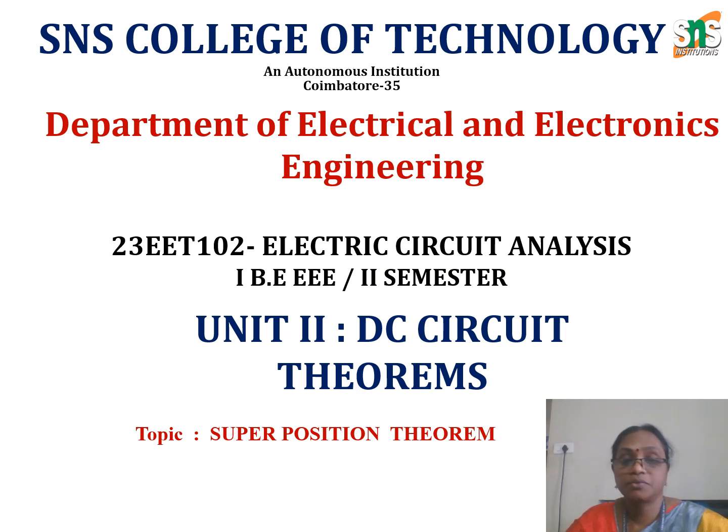I think in this session we are going to discuss the superposition theorem. I have to recall the previous session, where we discussed Thevenin's and Norton's theorems. In Thevenin's, we find V Thevenin by open-circuiting the load resistance. In Norton's, we short-circuit the load resistance and find the Norton's current, that is, IN is equal to ISC. Both together, we are solving the superposition theorem.